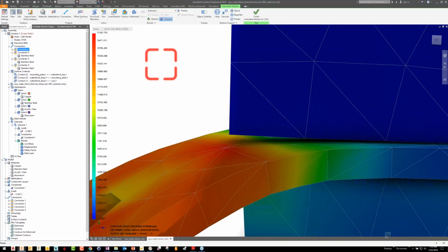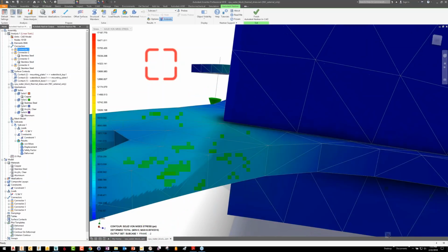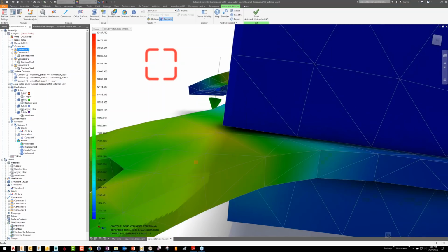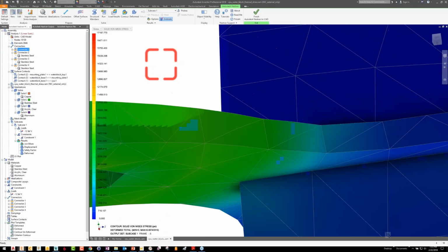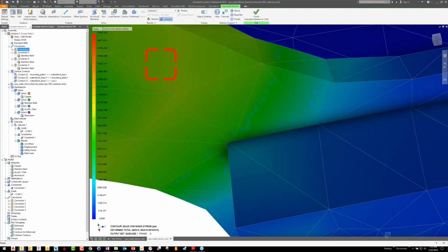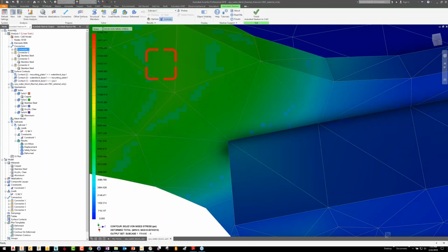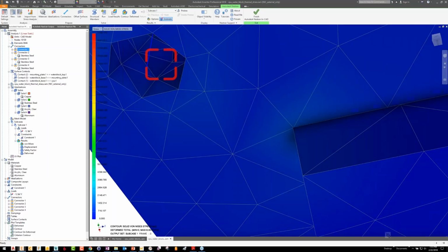And that's going to change the stress profile, not necessarily in the plate so much, though maybe a little bit, because earlier the plate was fighting the block and the block fighting the plate, so there was stress in that area that wouldn't be there in real life. See down at the bottom, they're not separating, but you can see them sliding a little bit. With a bonded contact, that wouldn't have been allowed, and they would have been fighting each other. Again, stress as they fight against one another unrealistically.